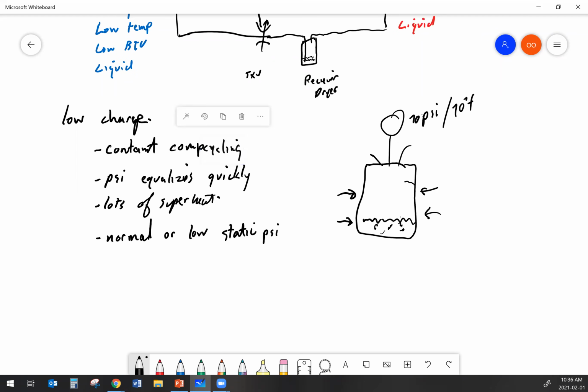And it doesn't matter if that refrigeration system is completely full of liquid or if there's only a few ounces of liquid left. As soon as that liquid is boiled off enough to build the pressure, if there was enough liquid to make that happen, it'll hit your static pressures. If there was not enough liquid to make that happen, all of the liquid boils off, and then your static pressure is lower. Just because you got the right static pressures doesn't mean you've got a full system.